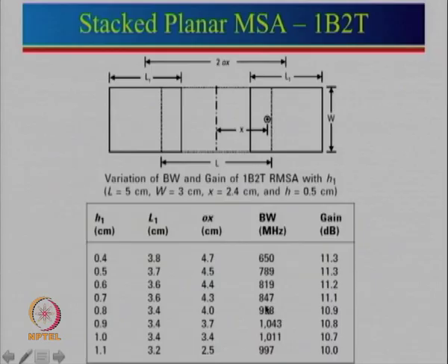There is only one small thing: here everything has been taken in the air. So, we need to provide the supporting structure, and that precaution one has to take. So, do not take these results as they are; you need to modify these things, because you need to provide a proper supporting structure, then only it will be a real practical antenna.